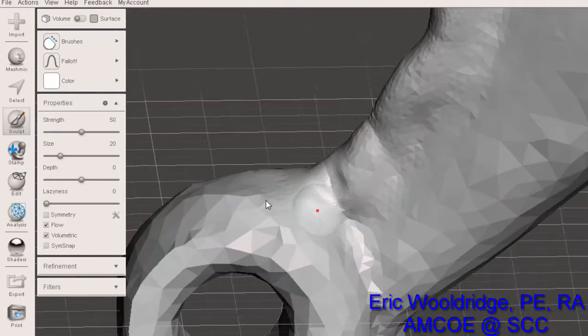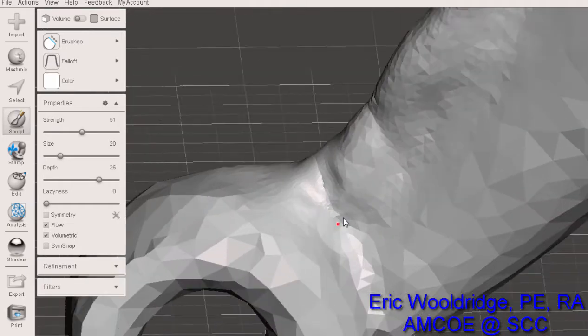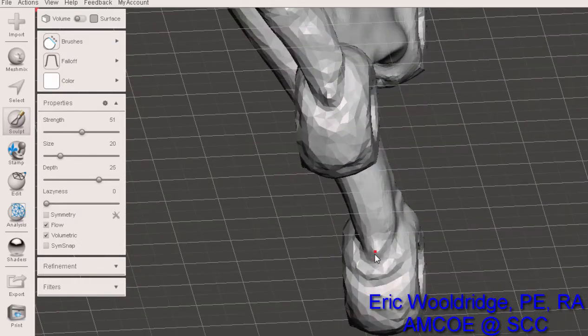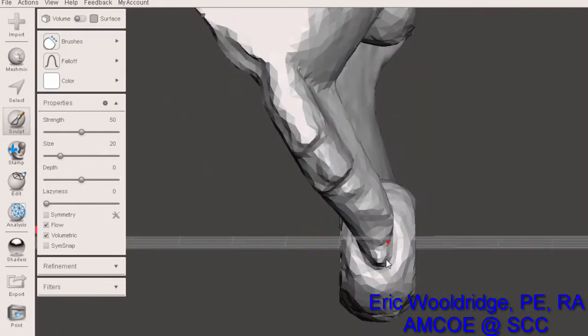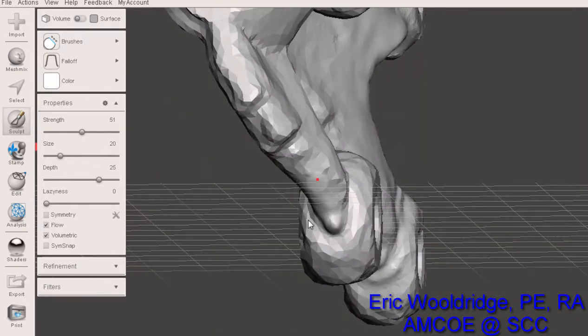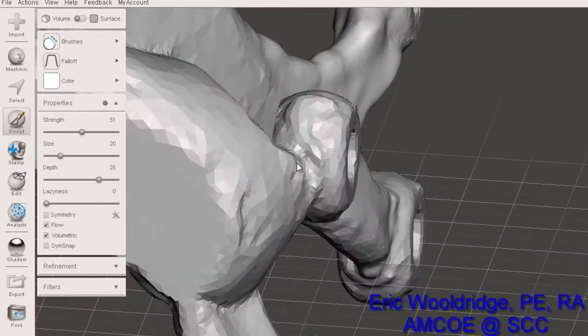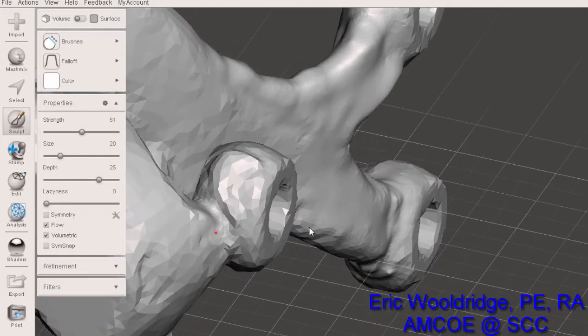So it doesn't really matter what file you're using with generative or what generative mesh you have brought in. A lot of times there is a little bit of cleanup necessary, and that's okay. That gives you the ability to kind of use some best judgment processes. You know, these little spikes that you see right here aren't good on it because it'll want to do weird support material at those spikes. And you want this thing to essentially grow uniformly.